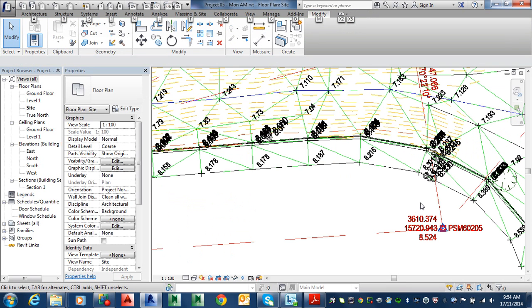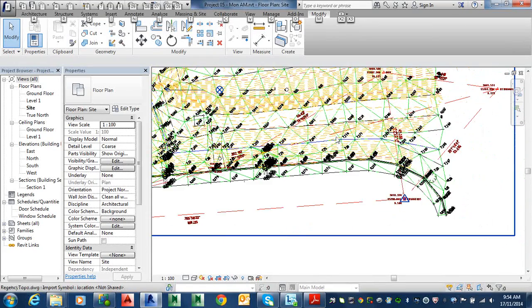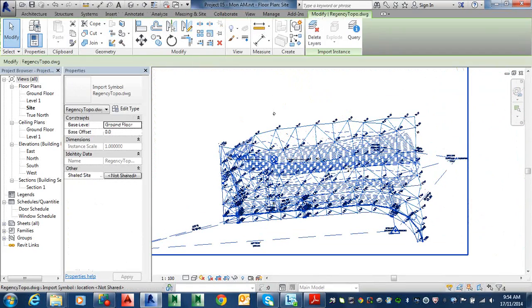All right. So basically, now I removed it there. We have locked on page 5. It says lock the survey point, using the clip, and pin the CAD link so that they are not moved accidentally. All right, so if we just click here, basically we have already locked the survey point. Now we're going to lock the actual contours so that they don't move accidentally.